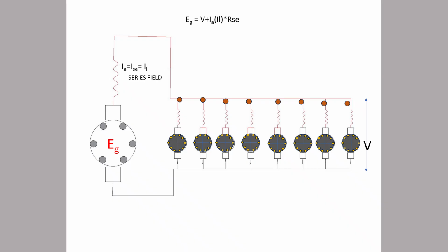So in our old electric locomotives, we were using DC series motor. Why DC series motor? Because it has good starting torque. When the train is stationary, to start it needs power, more starting torque. So from stall to start, we better use a DC series motor in electric locomotive. It will be helpful.